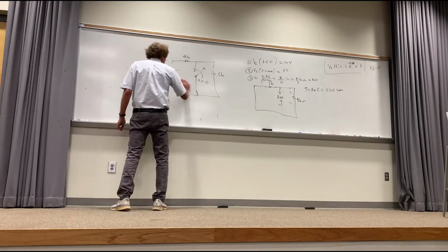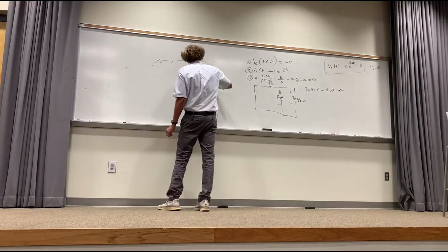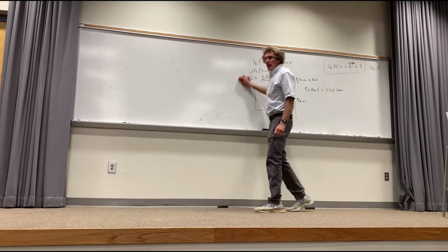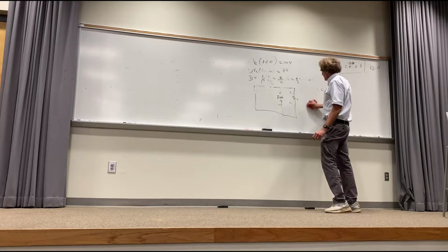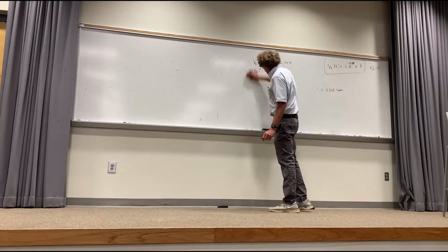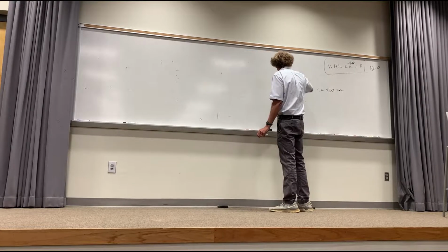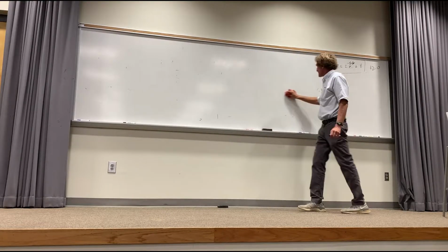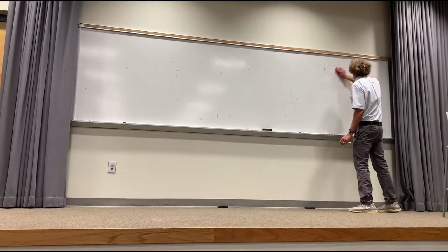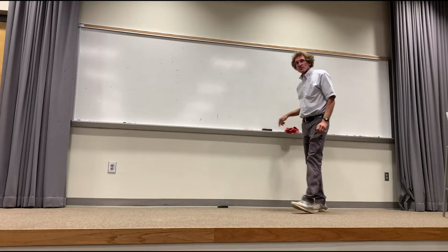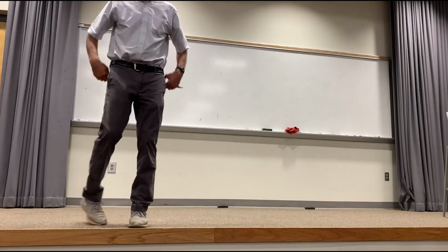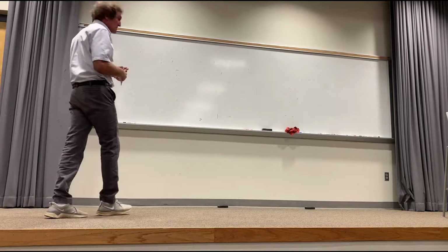Now these are simple RC transient circuits and LC transients. In the real world, there's usually RLC, but that's a second order equation, and we don't do them in this class. But if you're interested, you can take a look in the book, and there's solutions I put up there for second order solutions. For second order equations, what you do is write the differential equation and then take the Laplace transform. That's the easiest way. When I teach general circuits, that's how I do it.